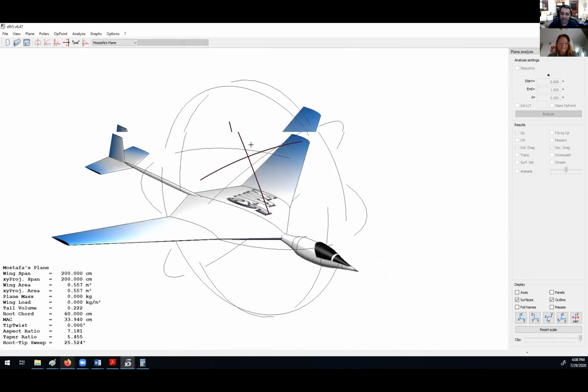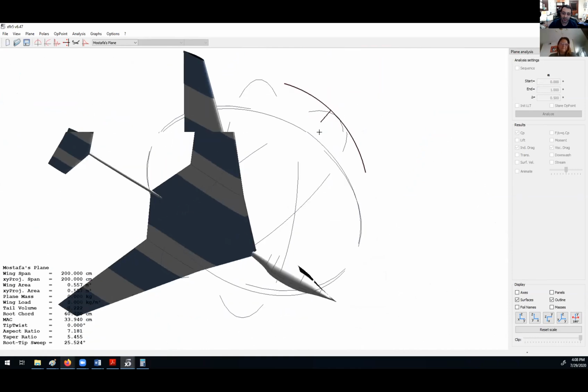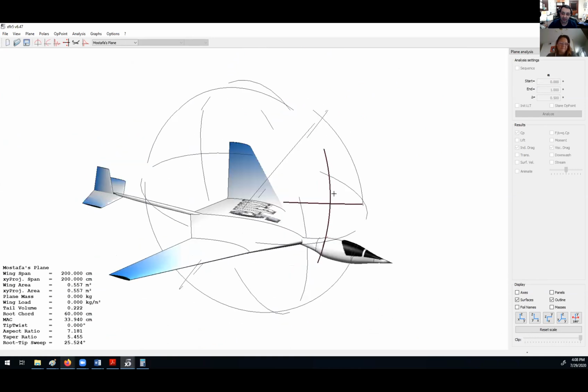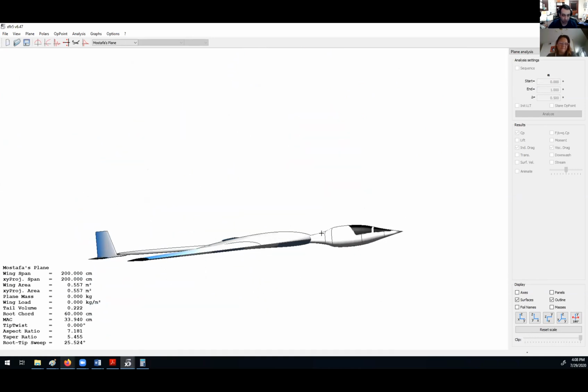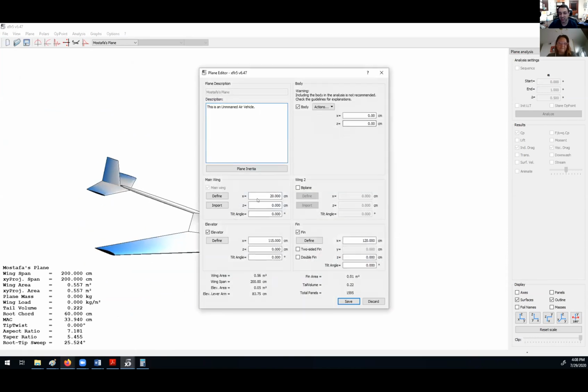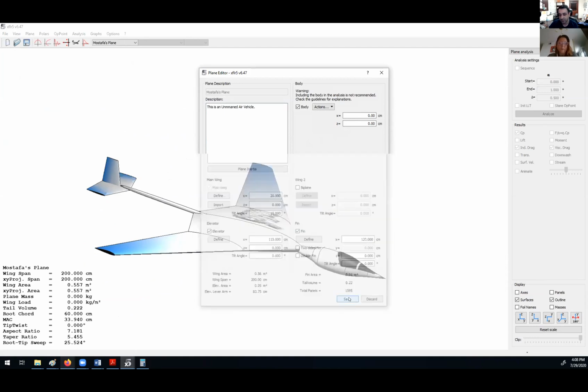Now let's say that this is your airplane that you have made, and you want to have an angle of attack for your wing. I want to angle my wing, the installation angle. This is a tilt angle here. I can put this as 0. Usually it's between 0 to 5 degrees, but to make it visible, I'll make it 15 degrees.